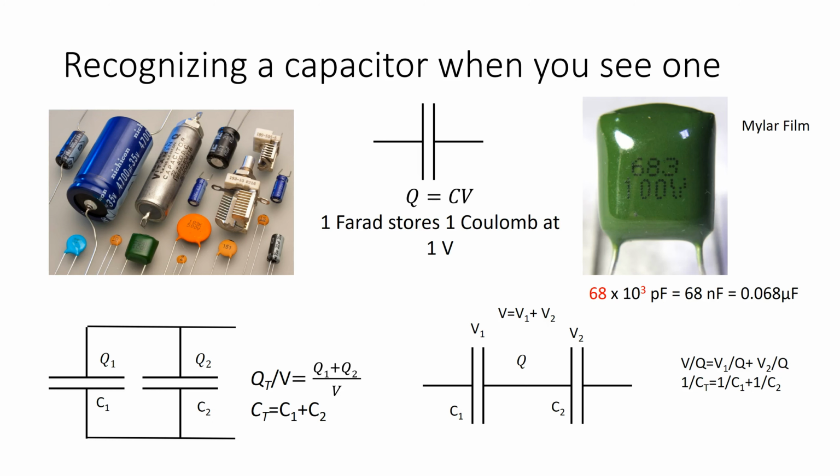So it's good to know how parallel capacitors add together. Meanwhile, series capacitors can occur because, for example, your oscilloscope lead can break, giving you a tiny capacitance in series with the internal capacitance in the oscilloscope. So for these reasons, it's good to know these formulae. Plus, we're going to use them anyway because I'm going to give you a lab to do in which you put capacitors in series and parallel. So let's just very quickly derive the results.